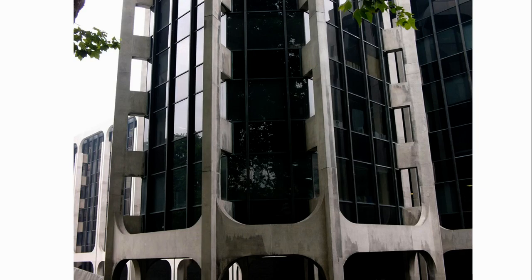This is nice because what you're seeing here is a rotated post and beam structure. The structure, as you know, we quite like is on the outside of the building, so you can see very clearly the logic of what's going on here. These are the elements. This is what's carrying the floors. So that's the depth of the floor. That's the spanning element that meets in the middle, and by rotating, there's the columns that are carrying the loads to ground. Here's the spanning elements. Here is a little Vierendeel truss, if you remember, that is just bracing each of those columns that are rotated on plan.